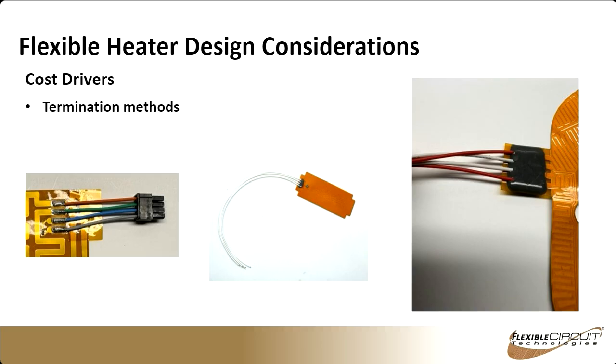There's a reference to a flat lead thermistor such as a B3950 NTC. I'm not familiar with this one in particular, but basically any component you could put on a rigid PCB, we can put on a flexible heater. We do a lot of 402 and 201 NTCs. Those are probably the most common because they are very small. We typically do put a dot of epoxy over the top of them just to anchor them down so they don't move while the circuit or the heater is being handled.